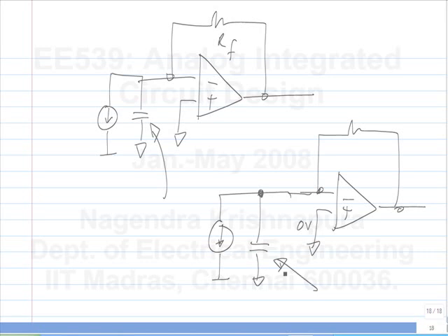So what is this capacitance? Why did we put it there? It's a diode capacitance. But can there be any other capacitance there? The input capacitance of the op amp. Because in this, I simplified the whole thing and said you call it diode capacitance. This can be anything. The op amp will also have a capacitance. And of course, any tracks on the PCB will also have a capacitance. So all of it can be lumped into that CD.